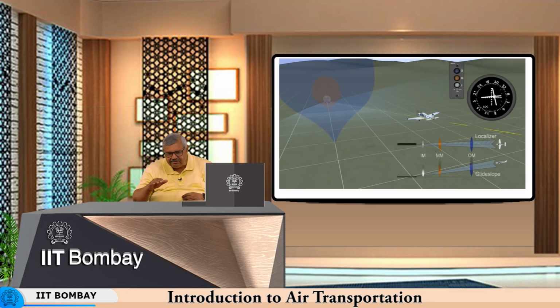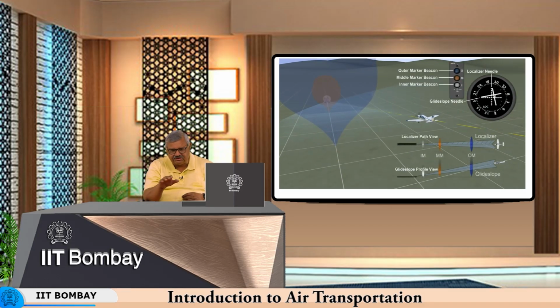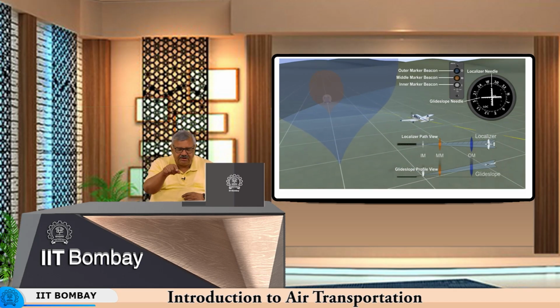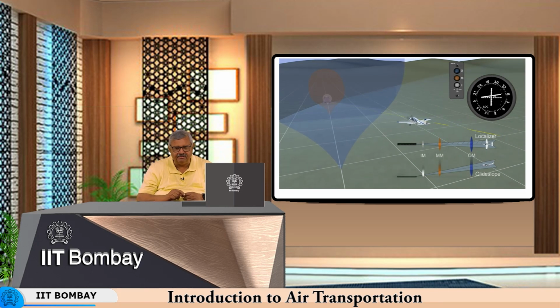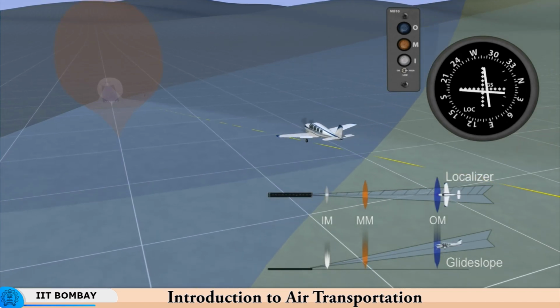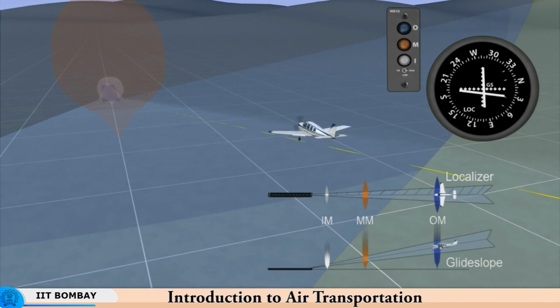But if you are deviating, if the nose is towards the starboard side, you can see. So, the pilot basically just tries to bring the crosses into alignment. Here it is going a bit to the left, and now it is perfectly aligned, and those are the 3 beacon audio warnings. So, you can see at the bottom that the aircraft is just about to reach the outer marker, and as it reaches the outer marker you will see the lights flashing and aural warning.